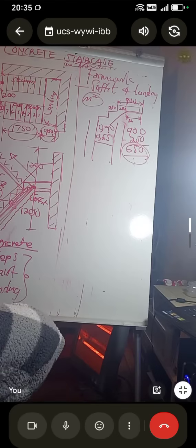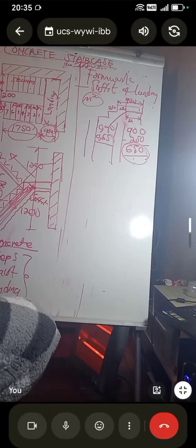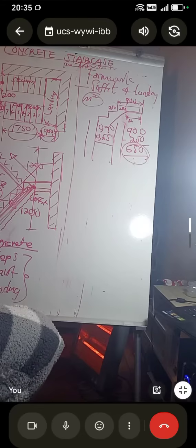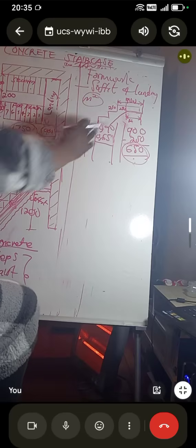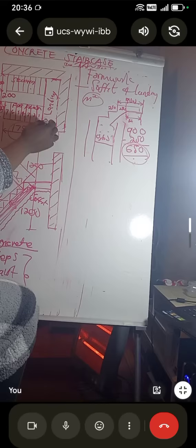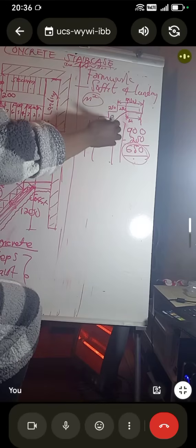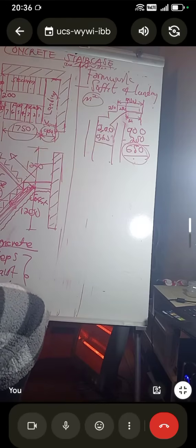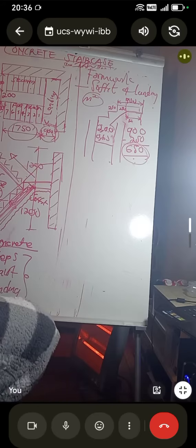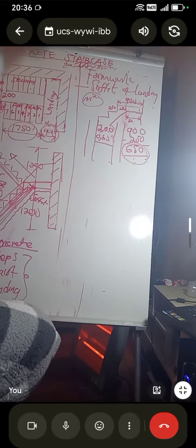Okay. Now, I use the length of the soffit. We only have one landing. Length of the landing. Yes, the landing. No, actually, the landing is what? The landing is the length. The total is 2,000. Sorry, from here to here. So it's going to be 2,000. There's a mistake there. You see? 2,044 is wrong. It's supposed to be 2,000 from here to here, and the width.